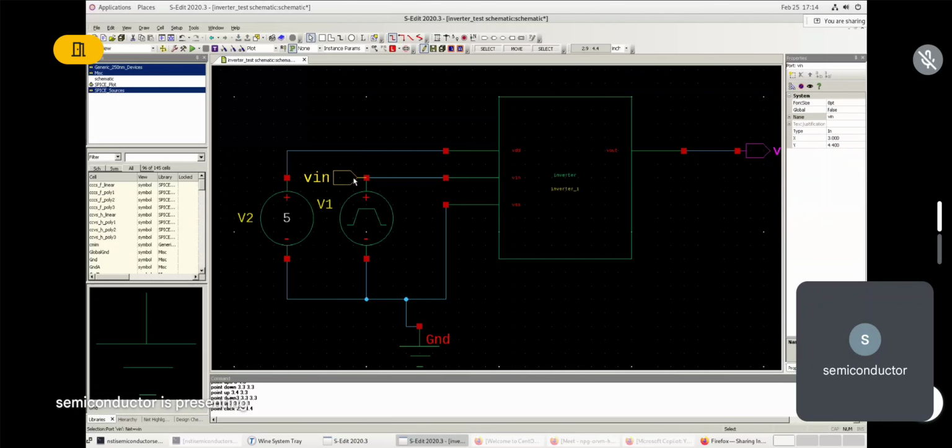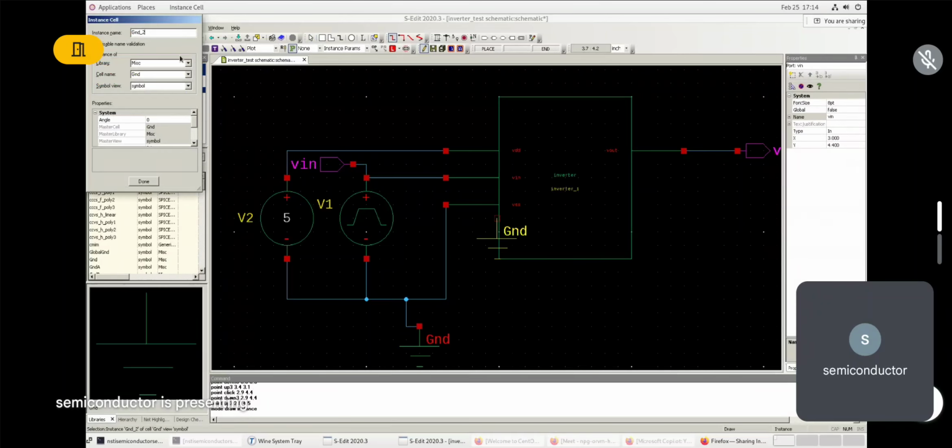Similarly, I will drag the V. Now I can go here and type I and go to the spice plot. Here I will have the voltage print. I can add the voltage print. Voltage print will be added only for the input and output for getting the waveform. So readily I will get the waveform and I will not get a plain window. The waveform will be displayed directly. If I don't add it, I will get a plain waveform window where I have to manually double click on V in and V out to get the waveform.